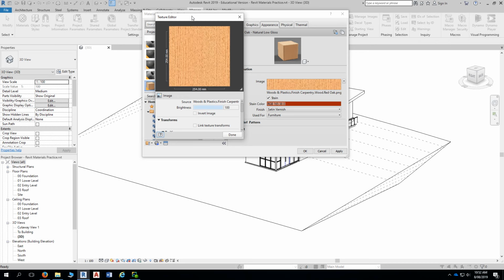You haven't got thousands of little tiny bricks. If you count the bricks in a standard wall that's 2.4 or 2.7, you should have a set number of bricks in that wall, okay? And if you've got 3 times that amount of bricks, you know that the scale's not correct. So these are the things you've got to do. You've got to create the material, apply it to a building element, and test it to see if it looks credible.